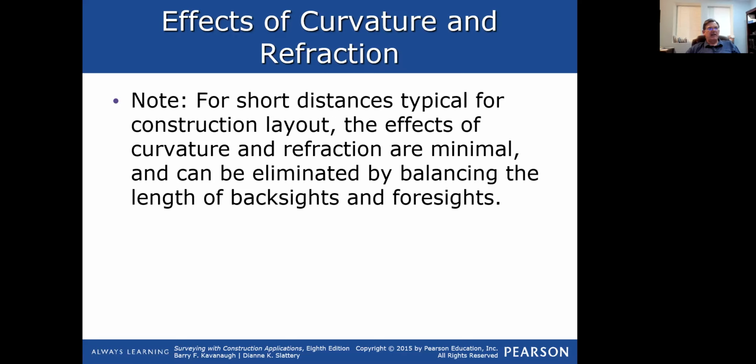But then that comes down 1/10 of a foot because of refraction, the light bouncing off the atmosphere. I want to think the number is something like that, about 0.7 or 3/4 of a foot, and in 1 mile you'll be looking higher based upon curvature of the earth and refraction of light.